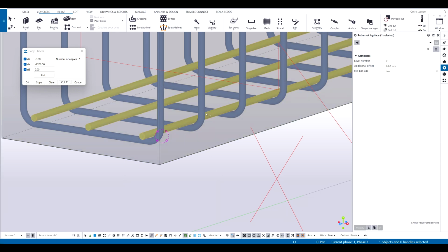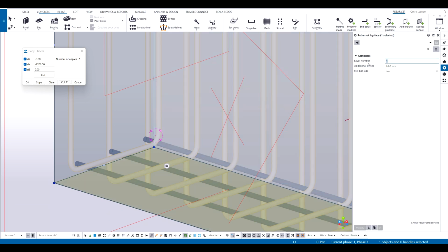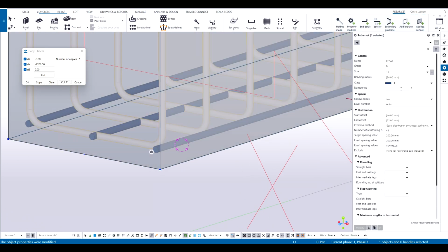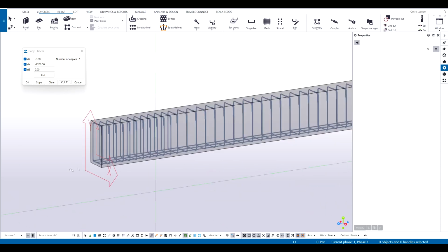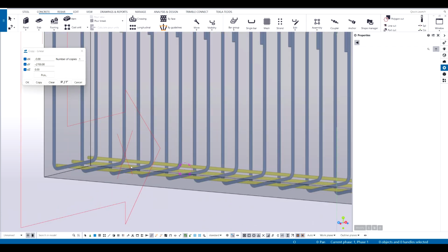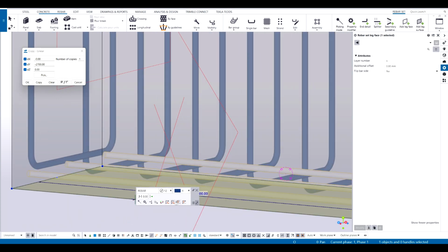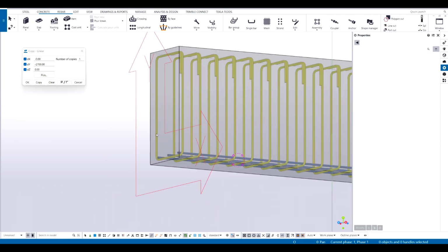So if I go to this one, if I make this layer 2, see, these 2 bars are clashing. Or else, there's another way as well. You can basically click on that bar, click here, this one, move to the outermost layer. So you see these bars flip over. Just imagine doing this with rebar groups. This is very handy either way.